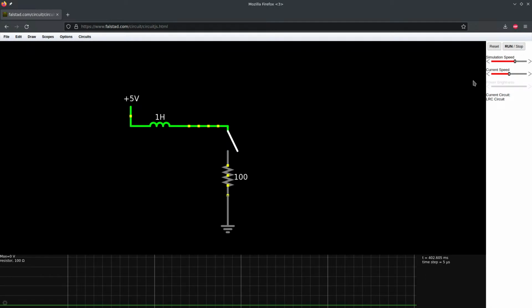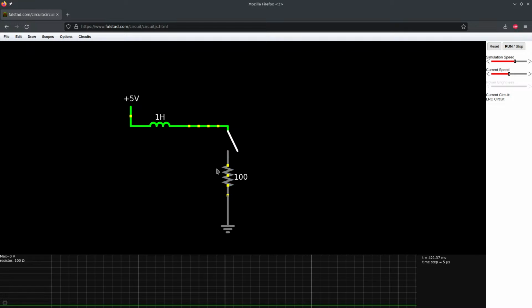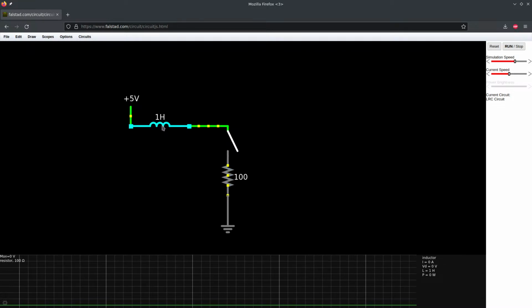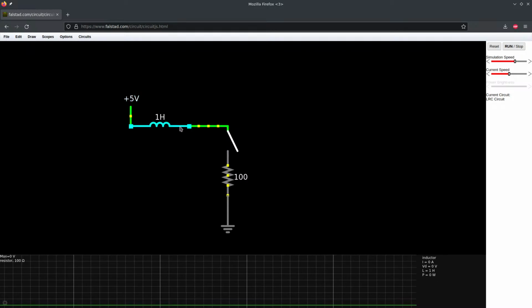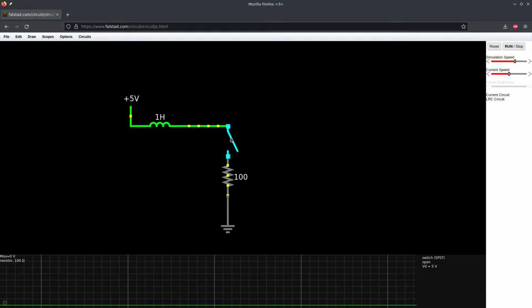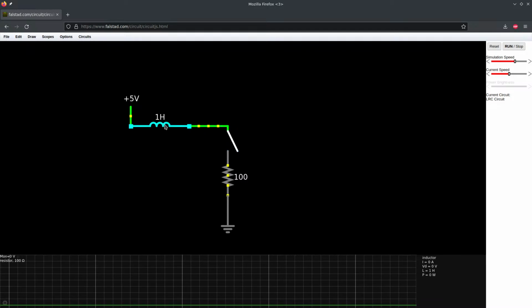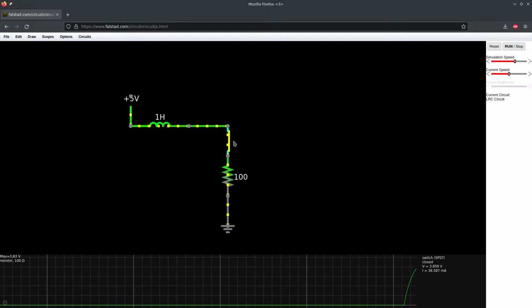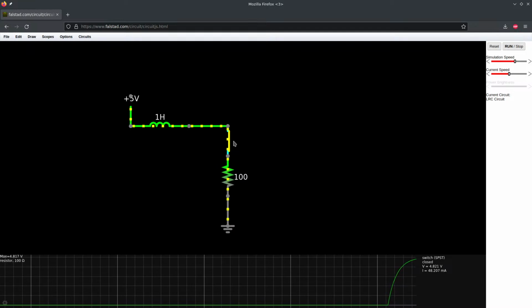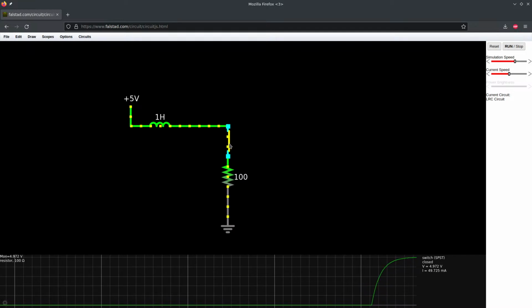Okay, so right now it's showing the voltage across this resistor over time. We have a fairly significant amount of inductance in the line here. So we have our 5-volt supply, but it's some ways away by a PCB trace or a wire or a cable. And the microcontroller is switching so fast that that matters, and it takes time for the current to change because there's inductance in the line. So you'll see the voltage that's here isn't able to change instantly when it needs to.